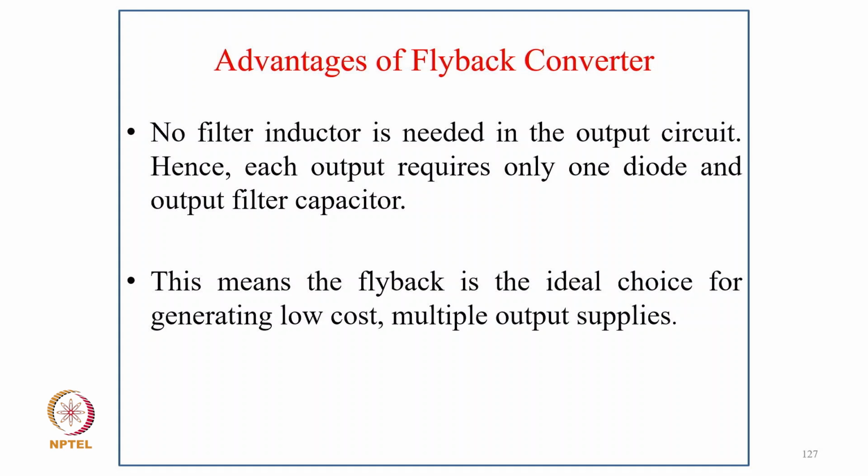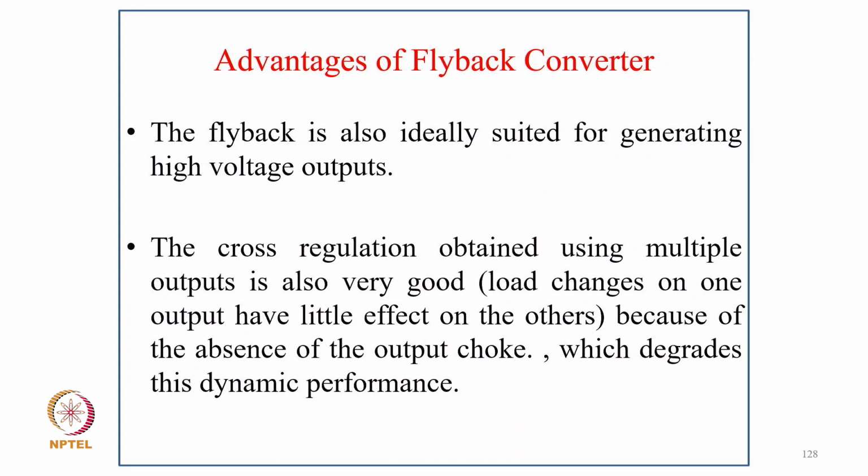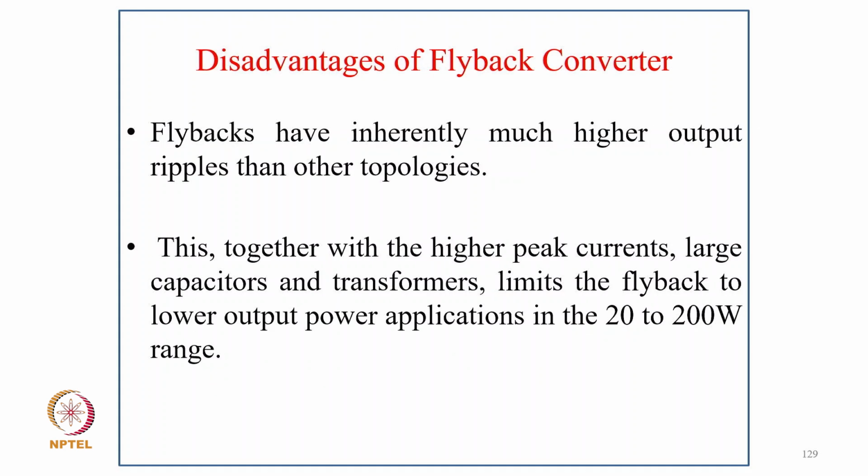So this means the flyback is the ideal choice for generating low cost multiple output supplies, and the flyback is also suited for generating high voltage output. The cross regulation obtained using multiple outputs is also very good. Load changes on one output would have little effect on the other, because of the absence of an output choke, which would degrade the dynamic response.